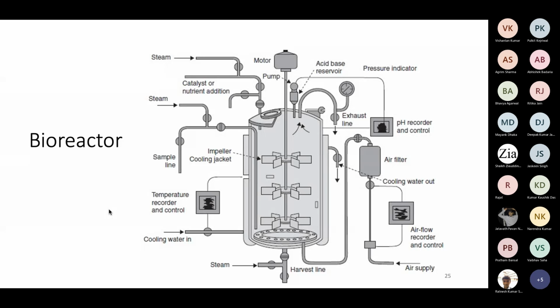So we use wood material or glass material or stainless steel material, and sometimes even in a stainless steel vessel you can have an inner glass lining. So you will have a bigger stainless steel vessel because stainless steel will provide you higher material strength. Now inside of that vessel will have glass lining to prevent any undesired reaction between the liquid component and the reactor material.